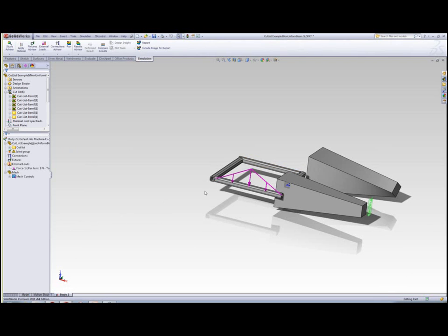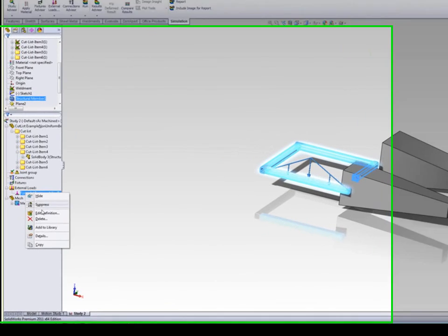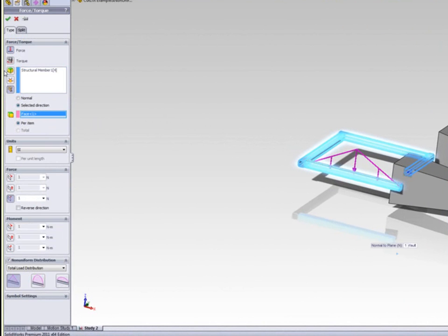If we take a look here, I have a force on this particular weldment, and I've applied a force. All I did was just apply a new force. Let me go and edit that. So I'll go in and specify beams for my filter. I've chosen that particular beam. I've chosen a direction. And now I have non-uniform displacements here.